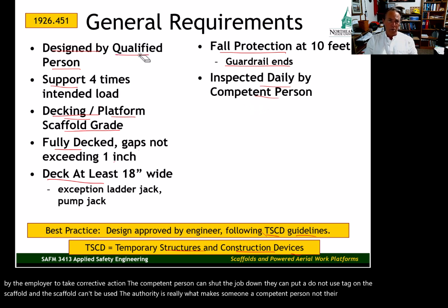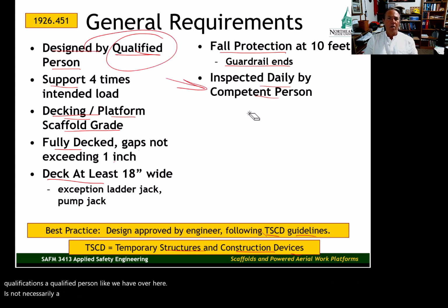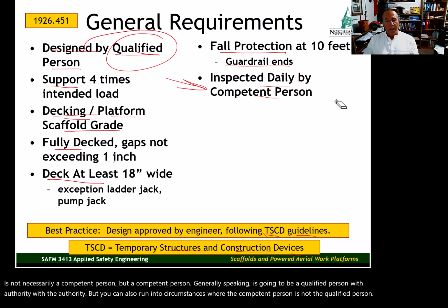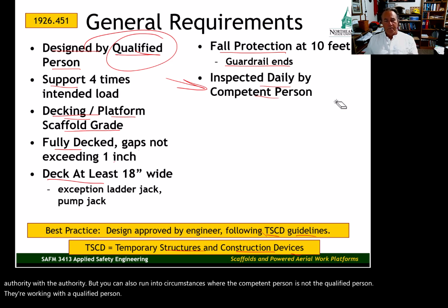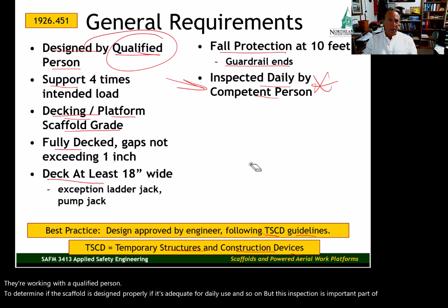A qualified person, like we have over here, is not necessarily a competent person. But a competent person, generally speaking, is going to be a qualified person with the authority. But you can also run into circumstances where the competent person is not the qualified person. They're working with a qualified person to determine if the scaffold is designed properly, if it's adequate for daily use, and so on. But this inspection is an important part of using scaffolding. It needs to be inspected daily.